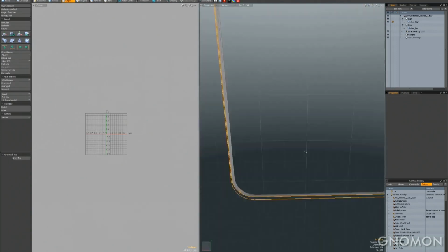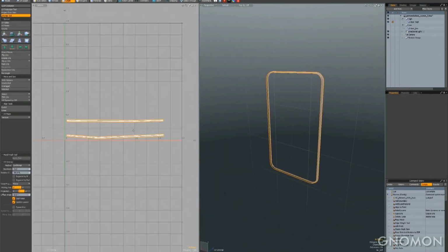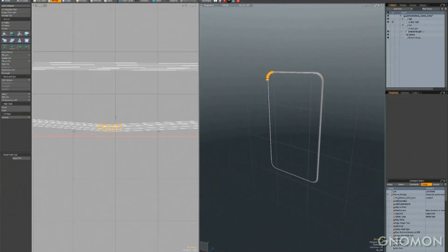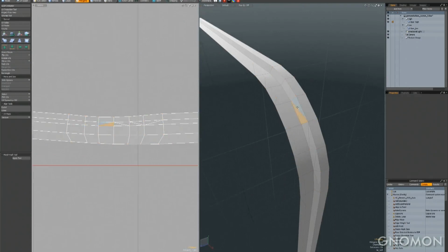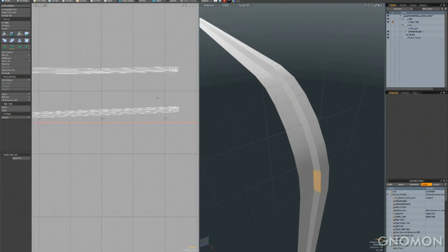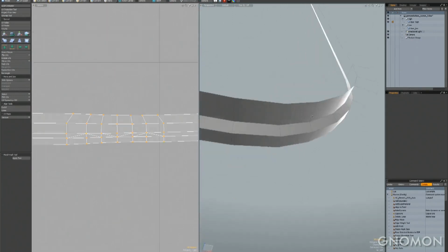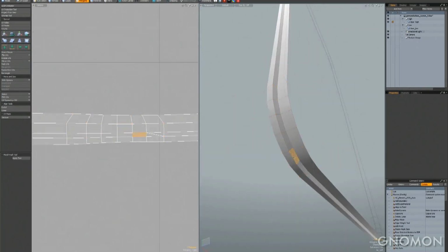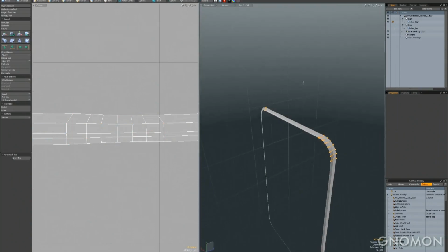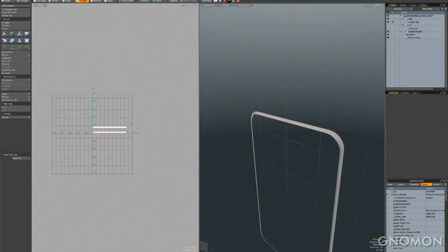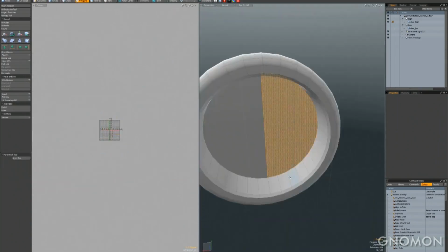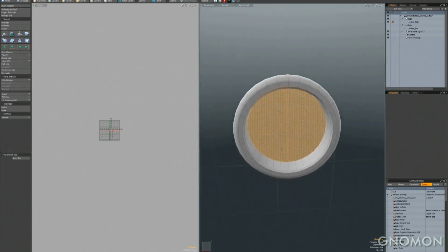So we're just doing the same thing right here, a little bit more of that, and we're going to run the command on this. And I'm going to go in here and clean up a couple of the triangles. Super easy, just using the same command that I was using on that Boolean object earlier to clean up the geometry. What it does is just combines everything into whatever you have selected. It's called the polymerge command. It's fantastic too. And we'll just make those into rectangles and finish out our low poly UVs with this right here.